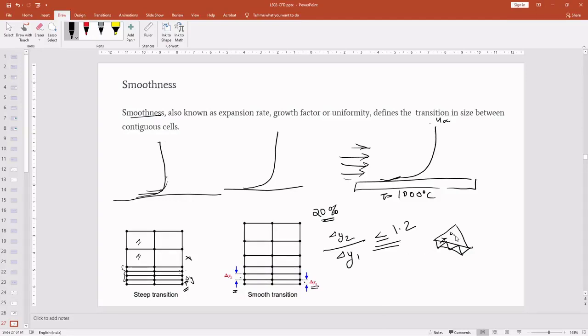So what I have drawn is triangular discretization. So this is a larger triangle. These are small triangles, but this layer should grow in a fashion that we can capture the variation, and also it should be smooth. There should not be sudden abrupt changes or jerks. Okay, that is mesh smoothness.